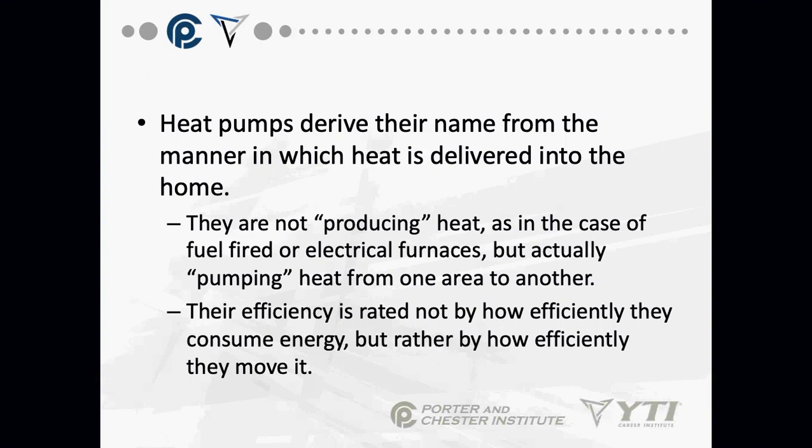So, yes, a heat pump will work under 32 degrees, but once that evaporator starts to freeze up, I have to go into a defrost mode. Okay, and I have to melt that ice off that evaporator coil. So normally, we try to use heat pumps in an environment or during the time of the year where the evaporator doesn't go under 32 degrees, which is the outdoor coil.